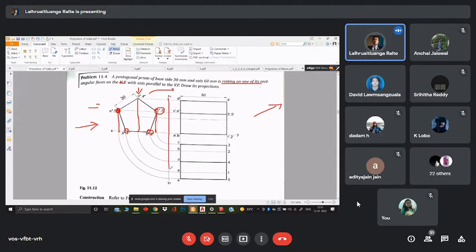on our X1, Y1 line, we can make an arc with this point as a center like this, as shown in the figure, or we can simply make a 45-degree line also, because it's still going to be the same 45-degree line like that. It's still going to drop at the right point, and from there we are going to project it on the right side.